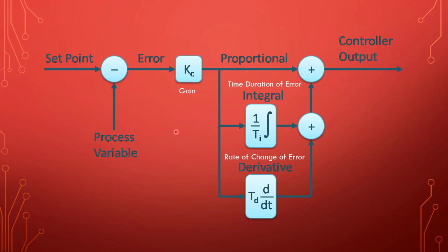And as it starts to heat up, the air will come down, but it can never get down to the set point, because if it did, that's not enough fuel to get to the temperature that it needs to be because of the disturbances. So this type of controller has a lot of advantages over on and off because you don't have the oscillations, but it's not completely ideal.